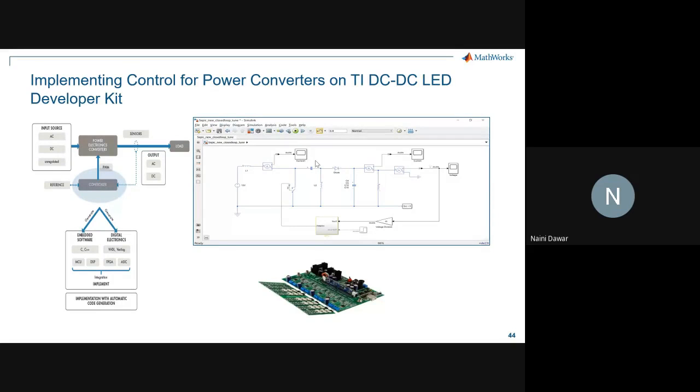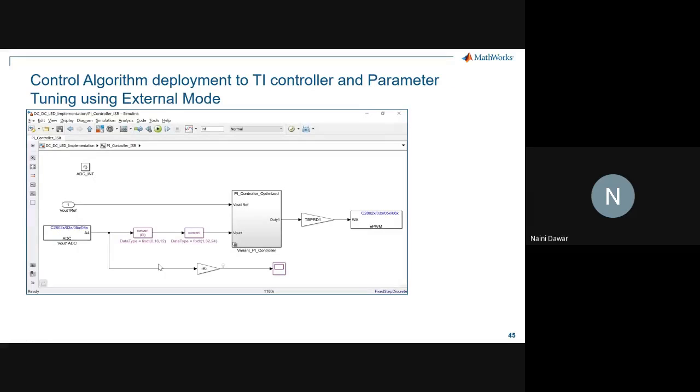We have had very good results with educational research scholars who have been making use of these hardware support packages for automatically generating the code for their controllers and deploying it to the Texas Instruments hardware. You can generate the C++ code, or the VHDL code if you're working on FPGA targets, and do the implementation. What this particular hardware support package gives you as a capability is that you will see these blocks in your Simulink library. These blocks are nothing but the device driver blocks.